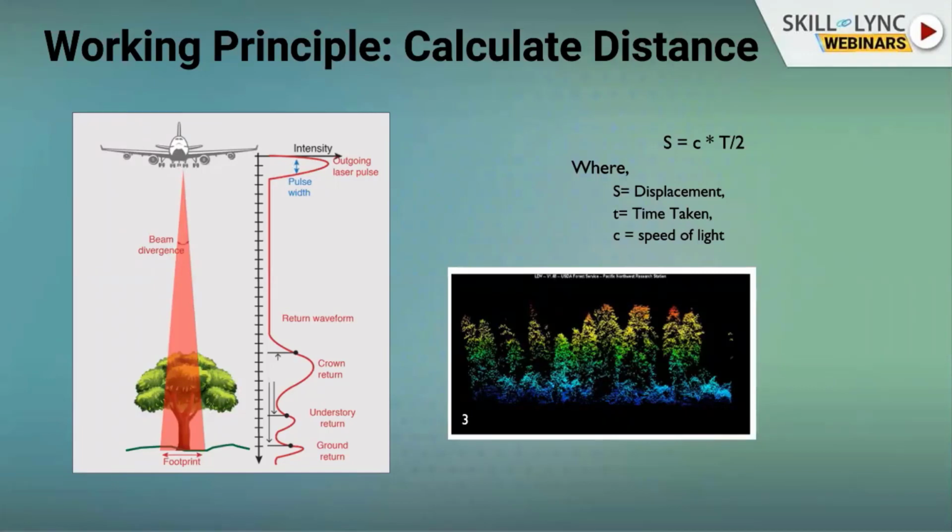So to measure the distance, the transmitter will transmit the beam and the receiver will receive it. And the IMU, or the CPU or other processing unit, will measure the time: when the transmitter transmitted the beam and when the receiver received it, what is the time in between. Because the light is going and coming back, it covers 2 times the distance. So we have to do t by 2 in our case to measure the distance only.